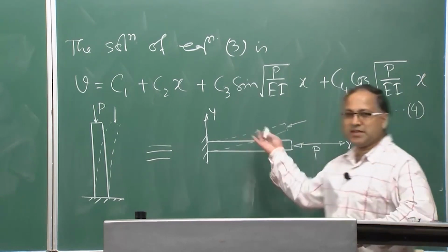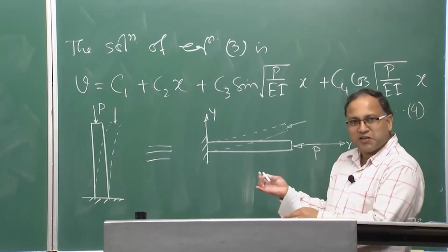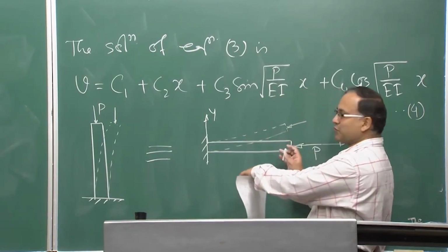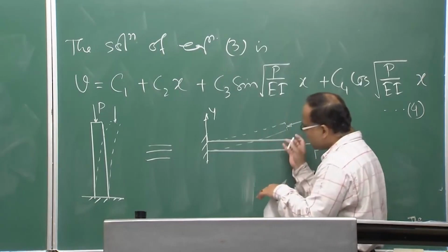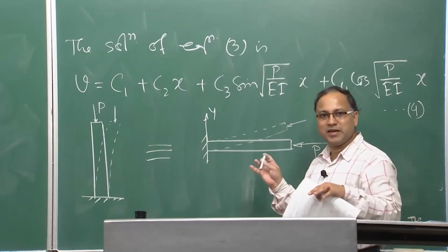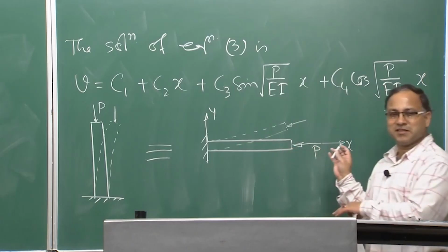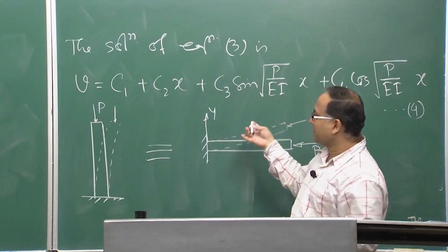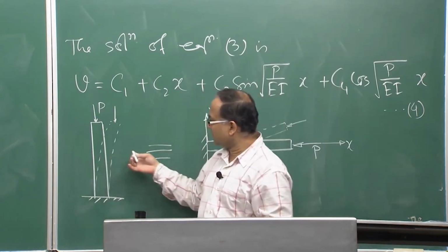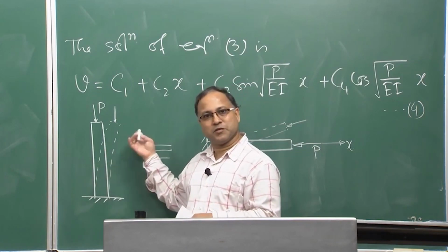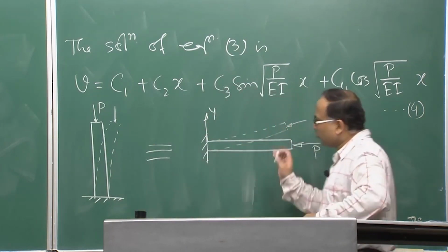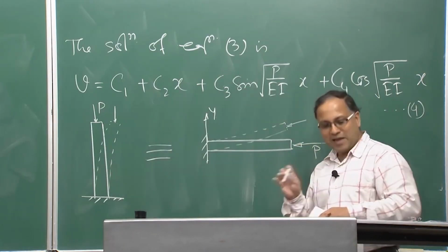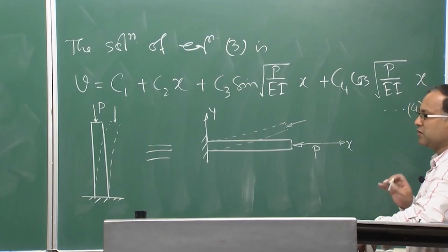Okay. So, both are same, only the orientation is different. It is the vertical, it is the horizontal. Because we are quite familiar with analyzing this kind of horizontal member, as we have seen in beam bending, we are considering it like this. However, this V here is along the y axis, if you consider this is your y axis. So, you can say that V is same. Whether we consider a column, vertical member or horizontal member, the analysis process and the steps involved are same.